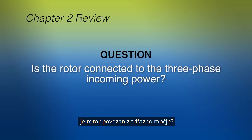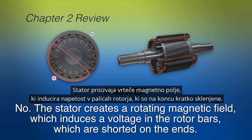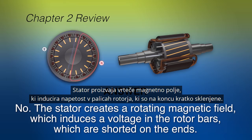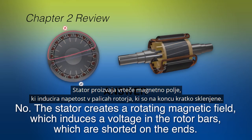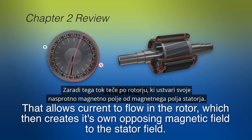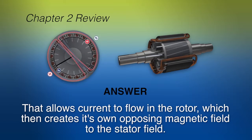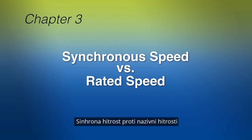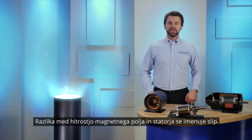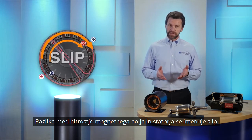Now, here's another question. Is the rotor connected to the three-phase incoming power? The answer is no. The stator creates a rotating magnetic field, which induces a voltage in the rotor bars, which are shorted on the ends. That allows current to flow in the rotor, which then creates its own opposing magnetic field to the stator field. The difference between the speed of the magnetic field and the speed of the rotor is called slip.